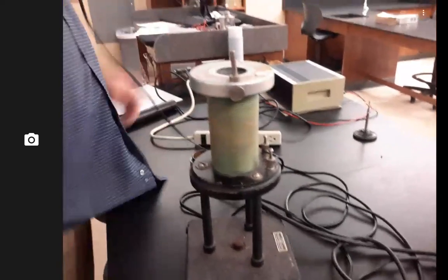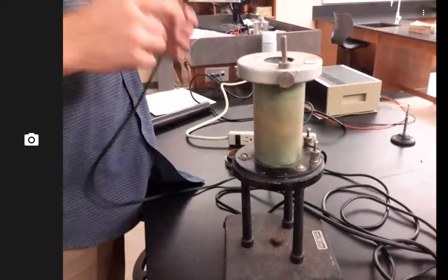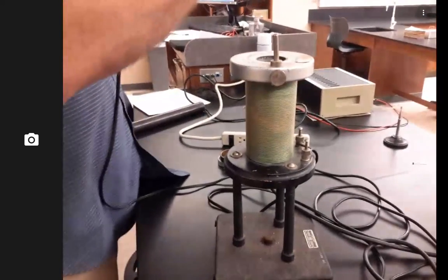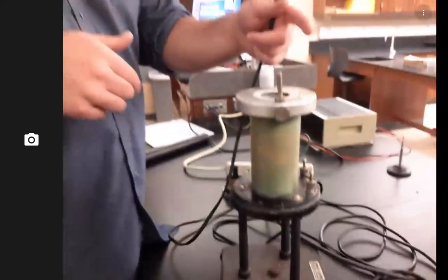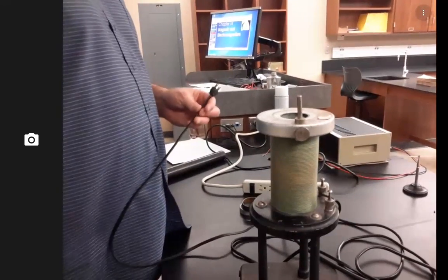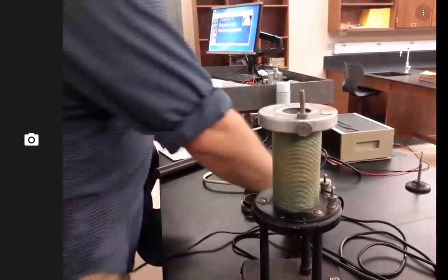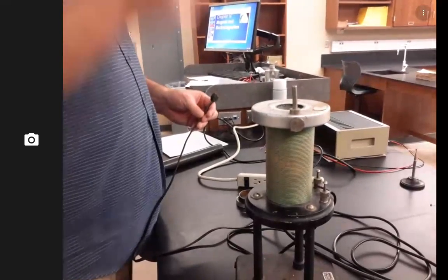Now one thing here is I'm plugging this into alternating current. Alternating current means that my current went one direction, making the magnetic field, let's say, come up in the middle, but then it shifted to the other direction, making the magnetic field go down. So the magnetic field was quickly shifting back and forth. And so that's why you heard this thing buzz some and get pulled in.